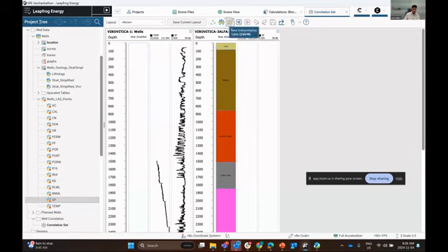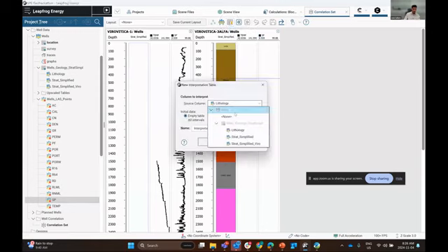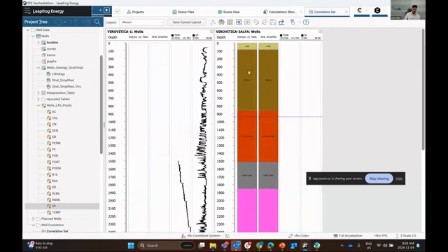If you needed to adjust the structure of the interpretations based on your well correlation, you can create a new interpretation table right here. So we can create a new interpretation table. We can copy from one of the original source columns. So we choose the strat simplified, which is what we built our geologic model off of. The initial data is going to be all intervals. We can call this interpretation table. So this is going to copy all intervals from this strat simplified, press OK.